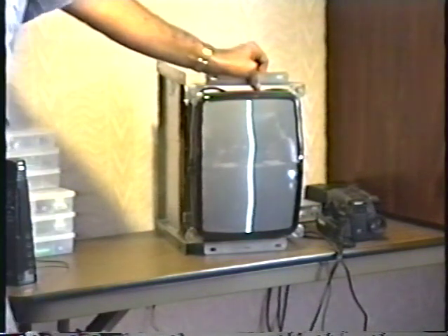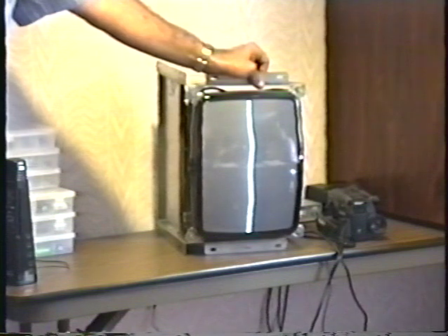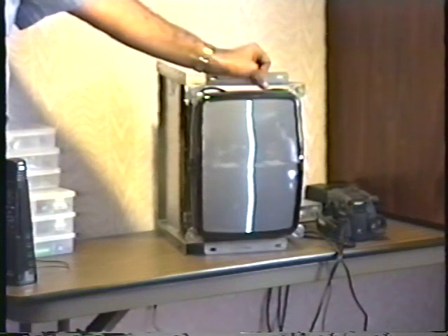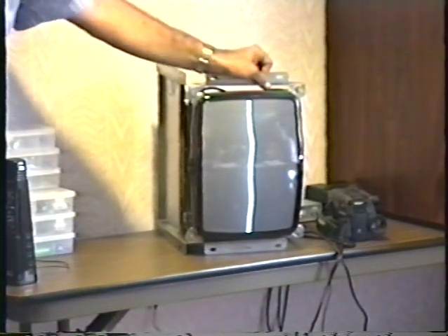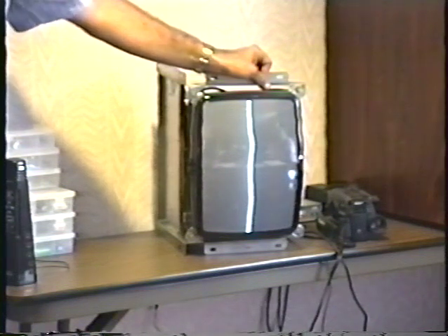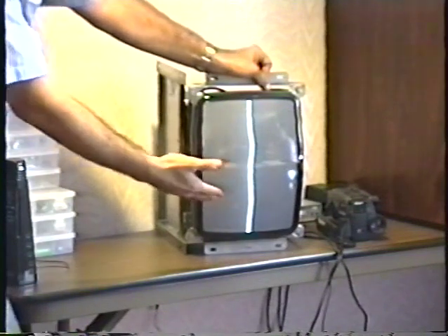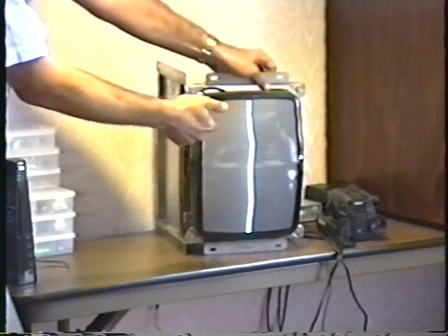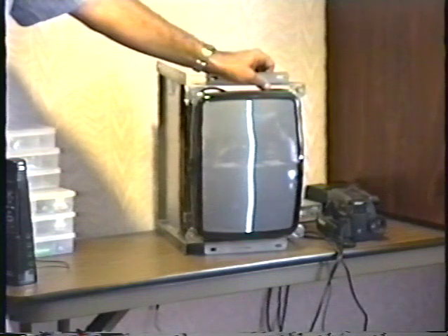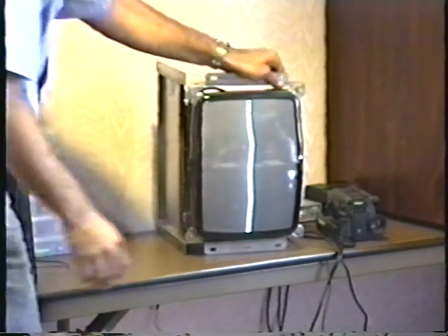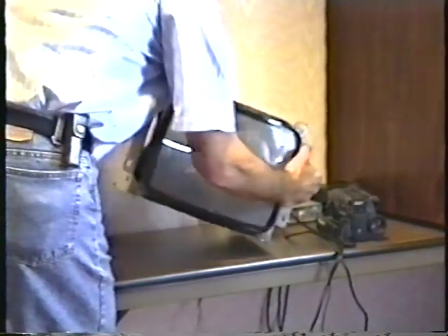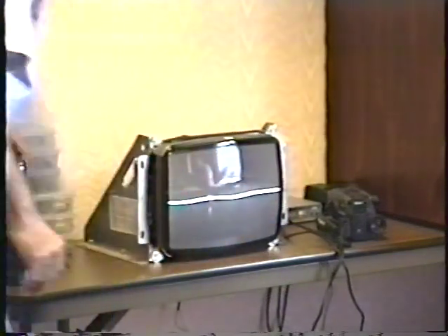This is a horizontal line. Right now you're looking at a horizontal line. I don't care which way that monitor is mounted. If you have a problem with a game and you call me up and say, hey, I've got a horizontal line, this is what I'm thinking. If you call this a vertical line, I'm going to send you in a whole different direction for troubleshooting because they're two completely different circuits. So the wide direction of the monitor is always the horizontal direction.